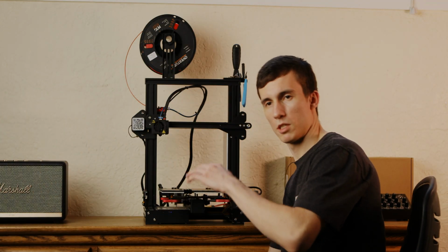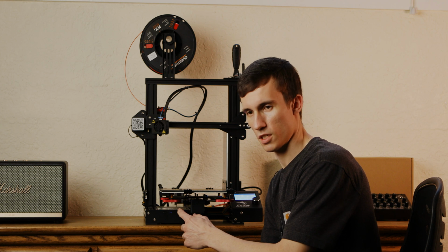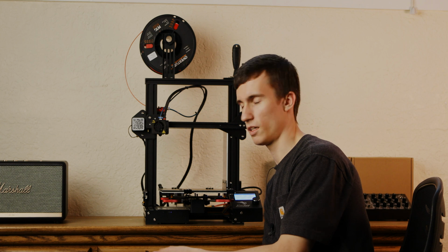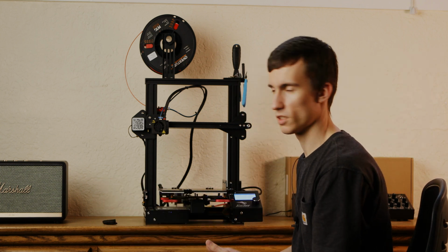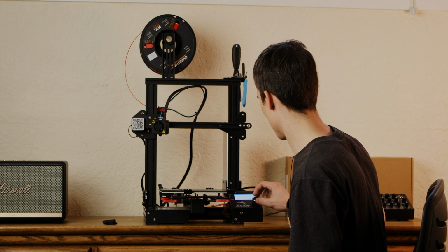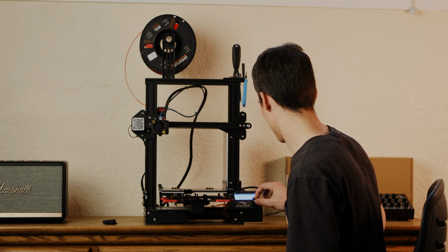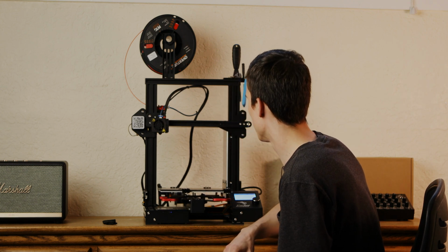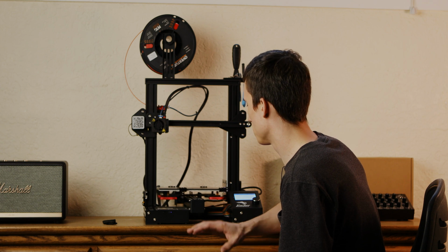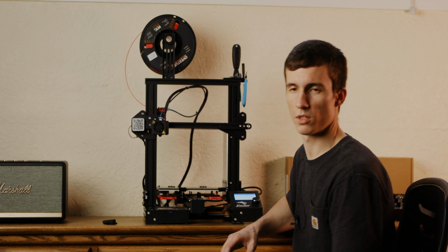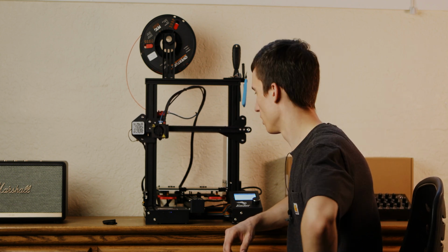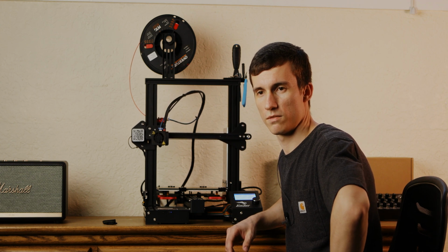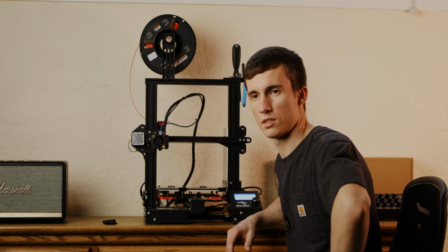I didn't put too much pressure while I was cleaning it because that may mess with the adjustment of the bed level. I still may have already pushed something out of level, but we'll find out in a second after I start the print. So let's get started. First thing I'll do is home the axes. Whenever something's moving and I'm just starting a print, this is the most error-prone time of the print, because you may have issues with adhesion, you may have issues with your G-code, you may have anything going on. Even your printer may have some technical problems.